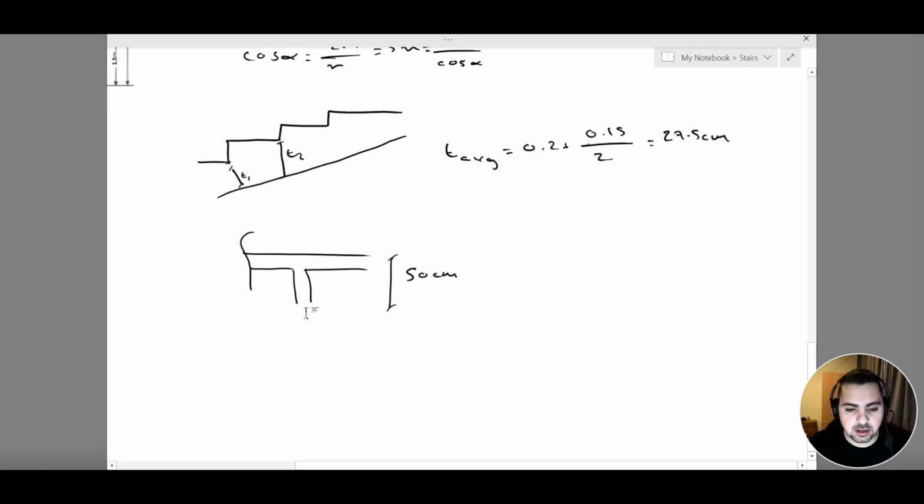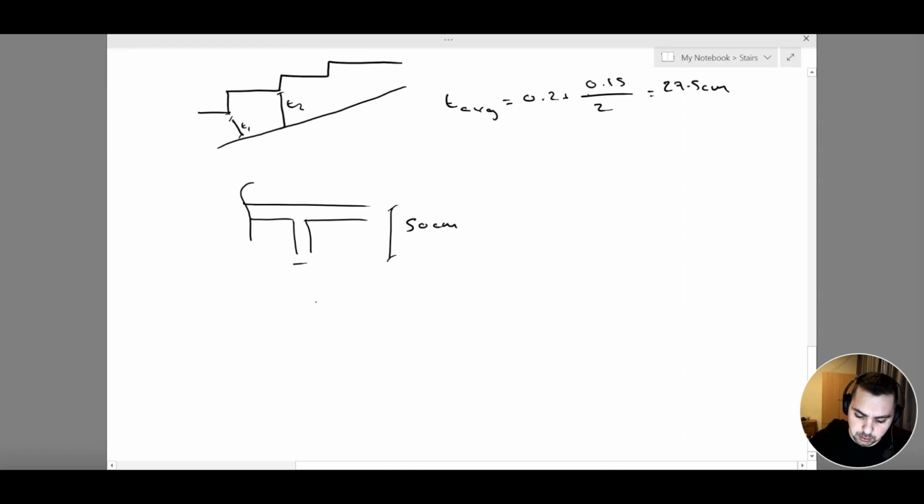And the width of my beam is going to be equal to my column's width. So this value here, we are going to take it as 20 centimeters, because when we are working with SAP, we are going to consider our column as a point support, and we are not going to actually draw our columns. So our beam dimensions are going to be 20 centimeters by 50 centimeters. This way we found the dimensions of both my beams and my slab.